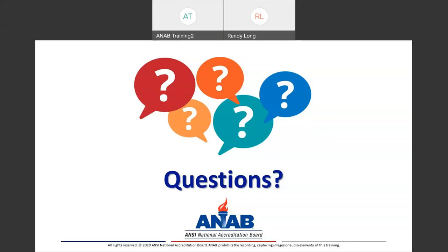Okay. The next question is, may I know if there are any references for acceptance limits of weights in analytical balances? For example, 10% acceptance limits for a 0.01 milligram standard weight. Is this a question about the acceptance limits on balances or masses? It says of weights in analytical balances, so I think they're talking about the masses there. In that case, it's the 3-to-1 uncertainty ratio.